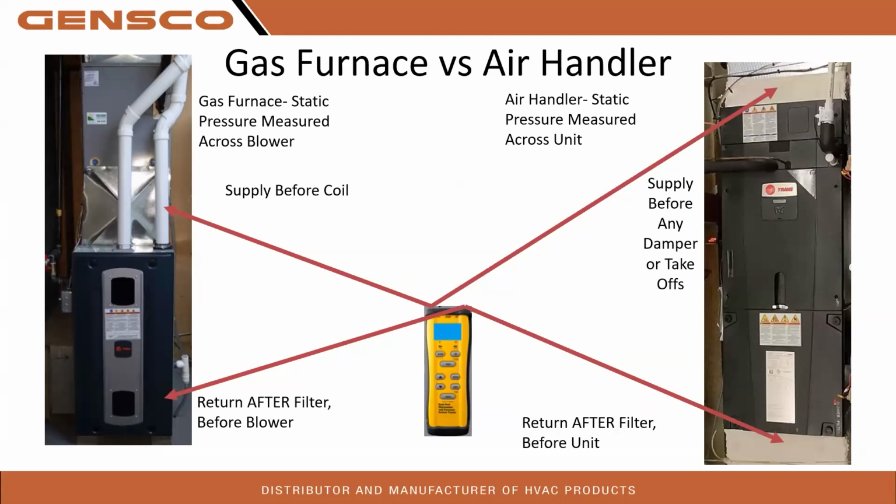Go to Harbor Freight if you need to, buy the little Christmas tree step bits, just enough to get to that sheet metal. Please do not use a 6-inch drill bit. It gives me so much anxiety when I see people do that in the field. I'm just waiting for you to go through that heat exchanger. Please don't. As you can see, this is how we are measuring our static pressure.